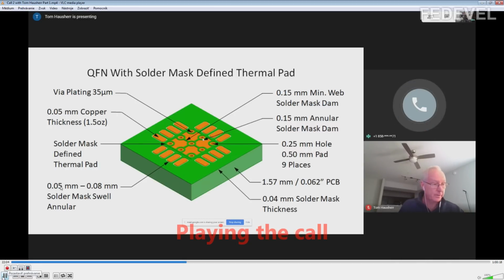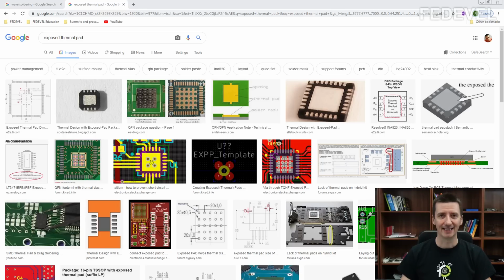But from my experience, if the hole in the vias is small enough, the solder will not go too much in. Or what is your experience? It will not go all the way through the board. Yeah. If the hole is small enough, the solder will go down the hole about halfway, and then actually freeze up. That's almost everything I wanted to ask about pads.